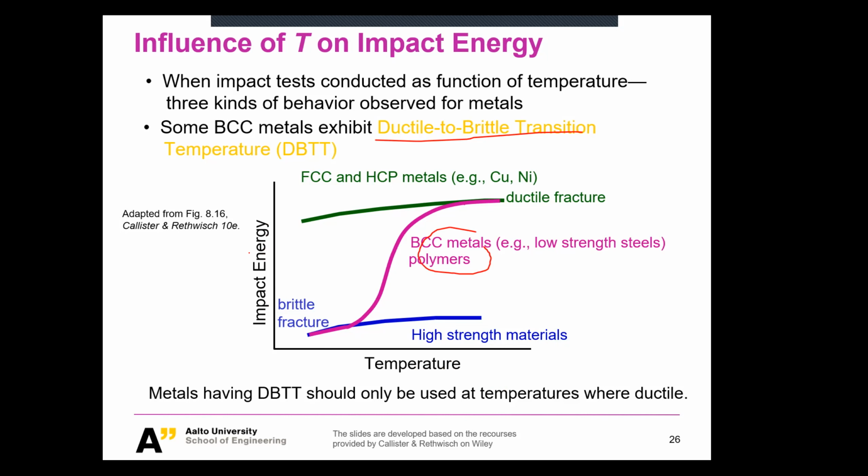By the way, this kind of energy is also called toughness. It is usually called Charpy toughness. So the KV value is typically also called toughness. As you can see, there are many toughnesses. So you have to really distinguish when you join a conversation or engage in discussion. When people are talking about toughness, always be clear what kind of toughness we're discussing.